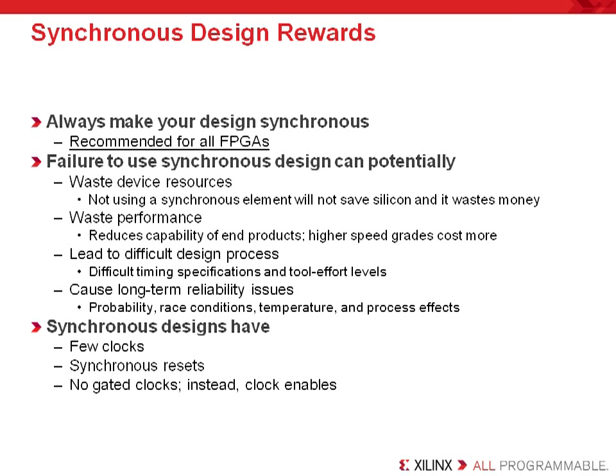Synchronous design works best for numerous reasons, most of which we explain in more detail in a later module, specifically the Synchronous Design module as part of the Essentials course. The most significant reason is that your design can fail if it maps to a different speed grade, device family, or product. This leads to a great deal of insecurity about the reliability of the design. It also wastes time, not just timing, but your productivity when you try to debug a design at a much later date. Synchronous designs have as few clocks as possible, use synchronous resets, and have no gated clocks.